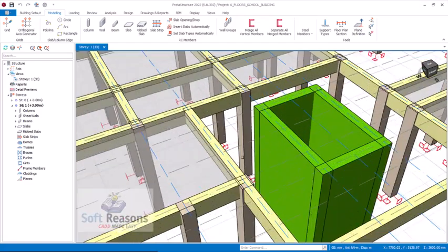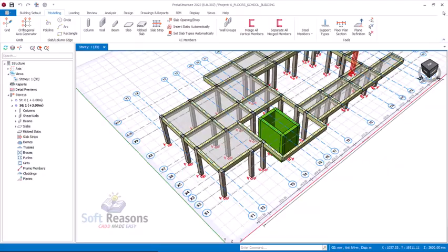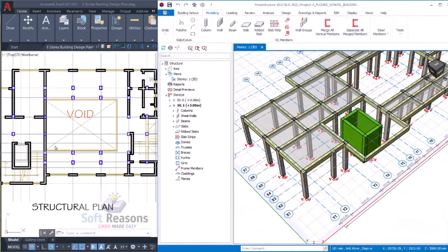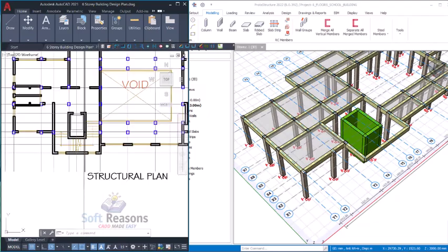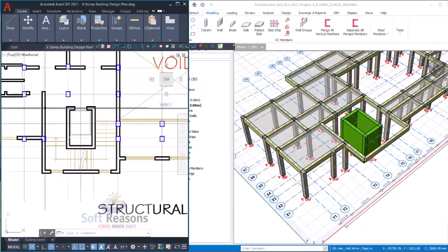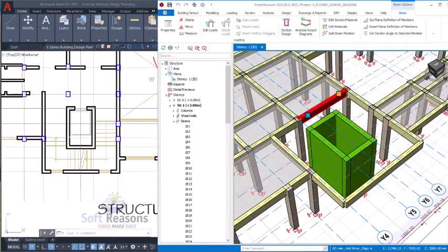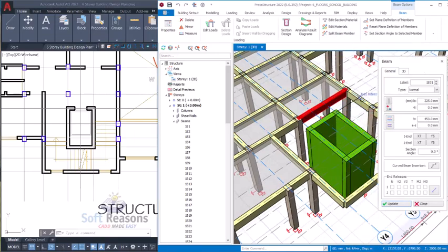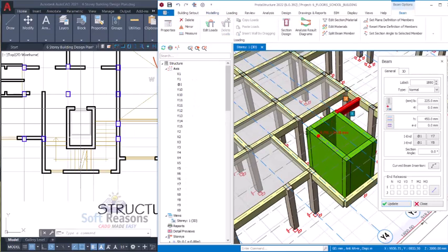So at this point, we are going to be having some beams here from what we have in the architectural plan, a structural plan here. We are supposed to have a beam here in these provisions. So we can't have a reinforced concrete slab right here. So I can select this beam, right click, click on it properties, something like this we have here.